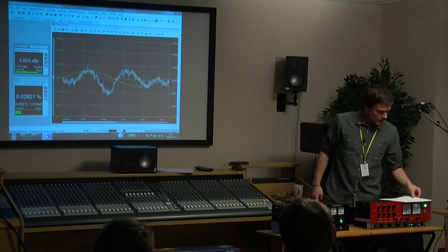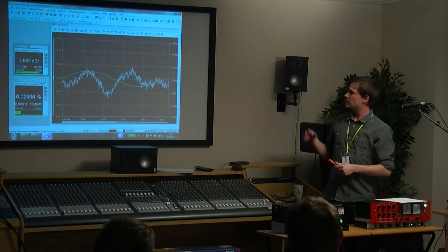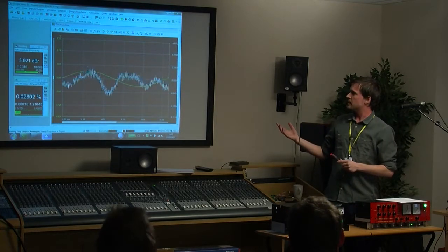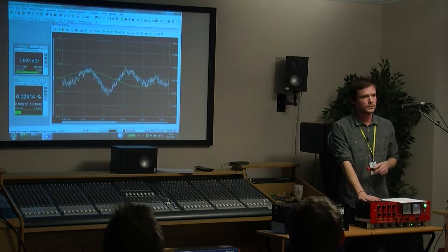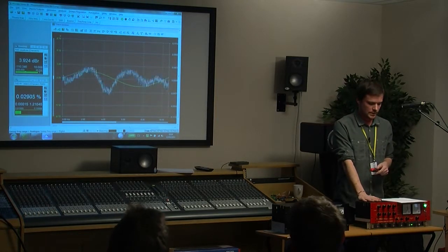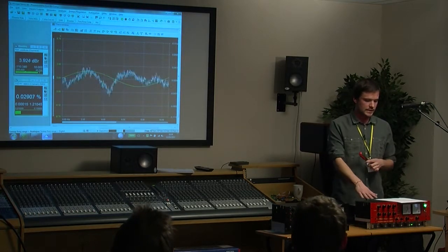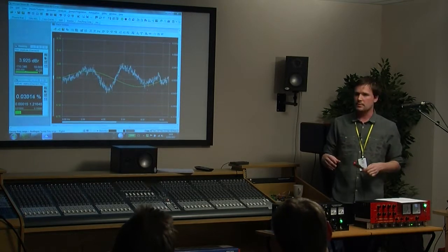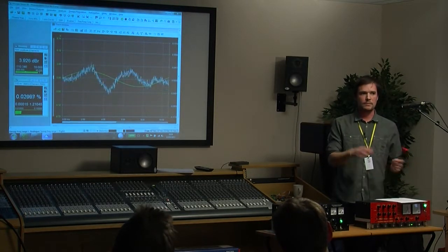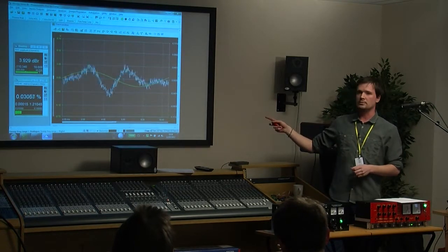But one option would be to use the relay boards that I just mentioned, and we could have an onboard testing procedure. We could use DSP to create a self-automated test procedure. We could have a program designed very much like our physical program to find this lowest distortion point.